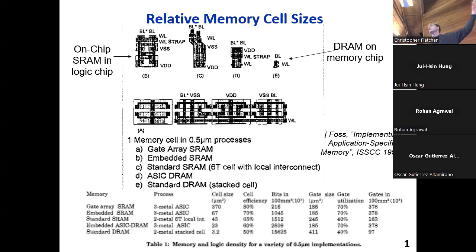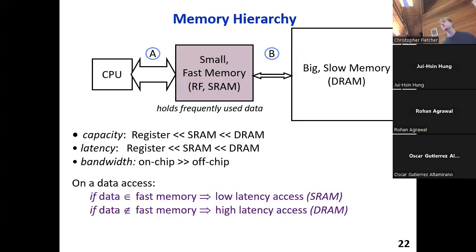The thing to take away here is that the DRAM cell is significantly smaller than the SRAM cell. This should not be a surprise, given the compare and contrast that we had with SRAM a few slides ago. But suffice it to say that access latency is proportional in not the direction that we want with cell size. You put these two together, and this is what motivates the way that we design memories today. We have a big, high capacity, highly dense memory, which is slow to access, as our main memory.